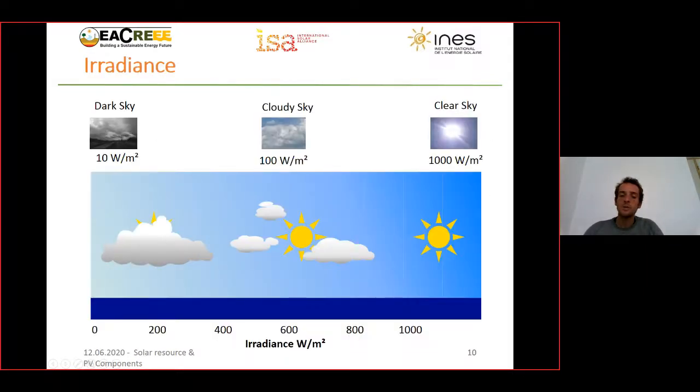Now, if we look at the values for both irradiance first and then irradiation secondly. Irradiance: I've just given to you the clear sky values for irradiance, which is 1000 watt per square meters for clear sky condition. It means a sky with no clouds, so a perfectly nice weather with only sun, so only a direct power from the sun.